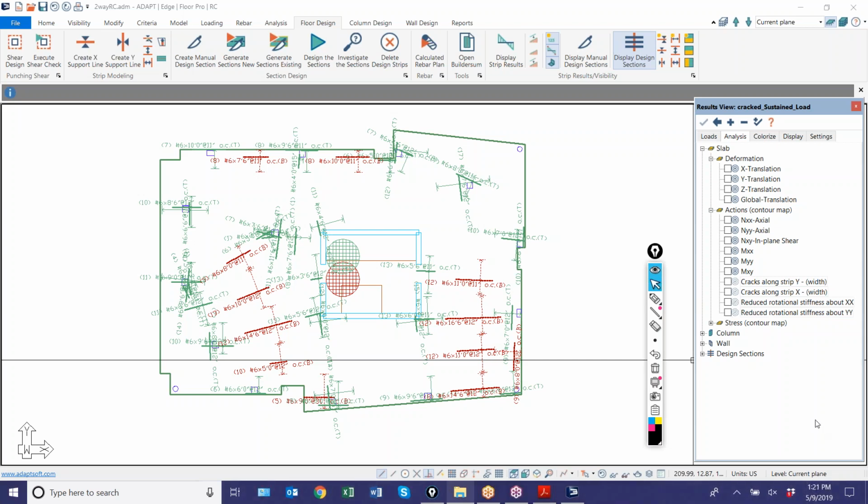The question was, for crack deflection, does the program include the reinforcement contributions? It includes it, I would say, indirectly, because we use the bilinear relationship between Ig and I effective, which is dependent on the cracked moment of inertia, which considers the presence of the rebar.